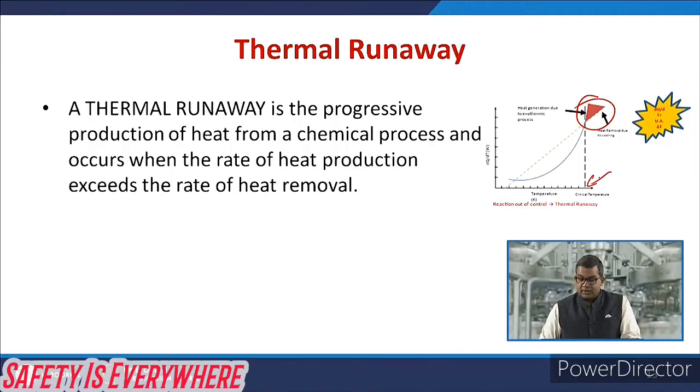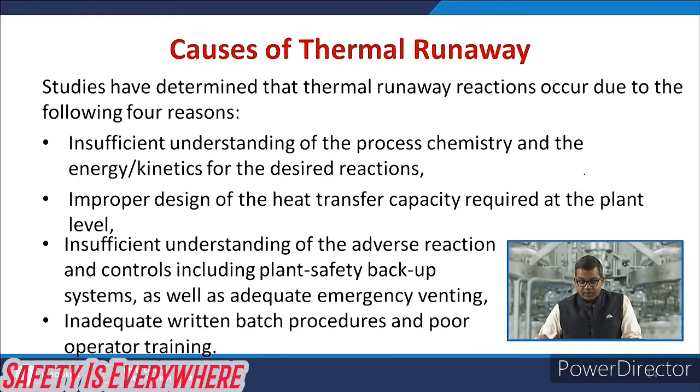Sometimes there are inadequate written batch procedures and poor operator training, because the process condition may surpass this critical temperature zone, and if the operators are not trained to handle the scenario, then definitely the plant may land in trouble because of the thermal runaway aspect.